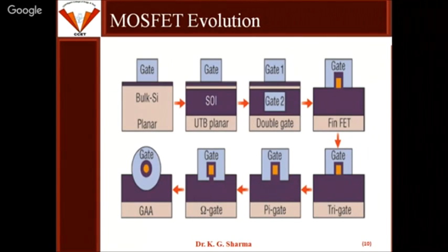But sir, by using GAA, we may have some disadvantages also. True. What about those? In case of reducing leakage current, parasitics will be more in that case. Yeah. If we are having the gate all around, then parasitics will be there. But if we compare with the previous generations and we are finding more advantages, then surely we have to move towards the gate all around.